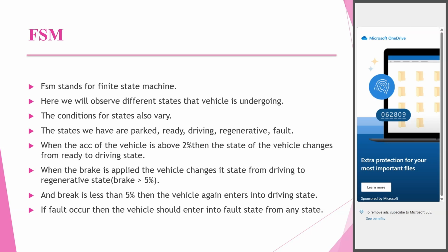First, the state machine. Here we will observe the different states that the vehicle is undergoing. The conditions for each state also vary. The states we have are parked, ready, driving, regenerative braking, and fault.